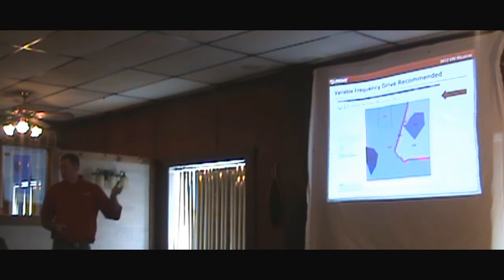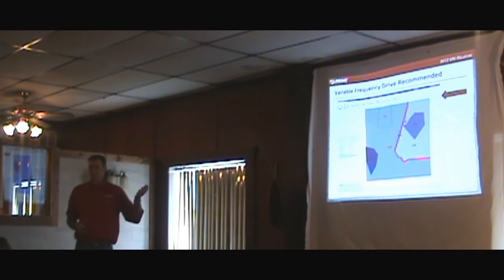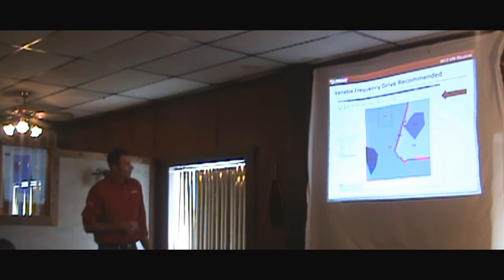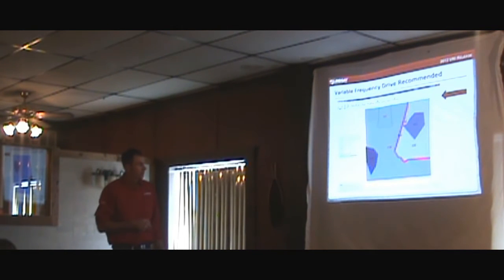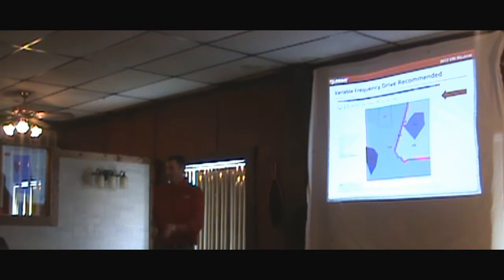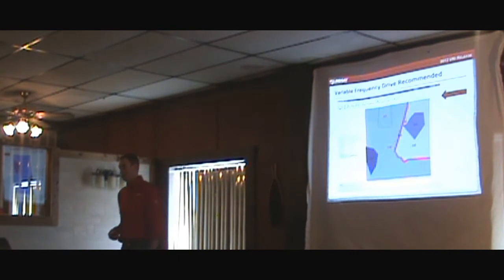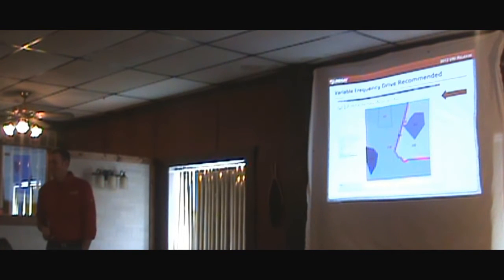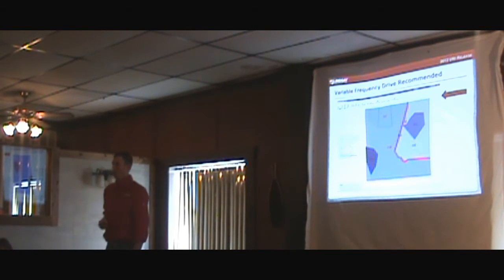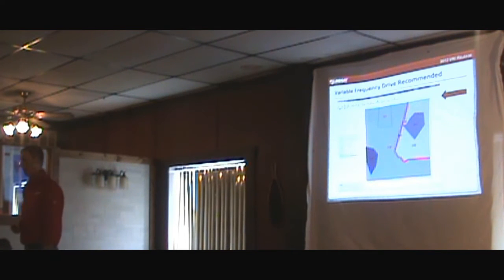We kind of covered this. Sometimes you need a VFD. I don't know if you can see this very well, but this red is an avoidance area, and that lines up parallel with the pivot. You can't shut off the whole pivot and upsize nozzles and make anything work. So sometimes there's a need. You have a question there? This is a very good fit for a VFD, right? Yes, this is an excellent fit for a VFD. That makes sense to me.